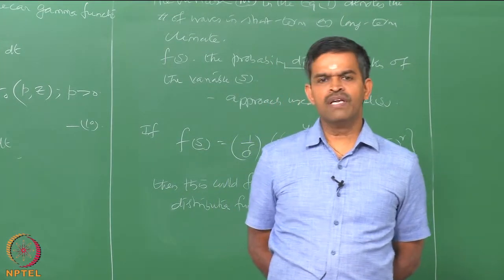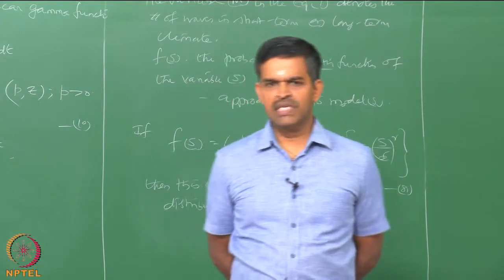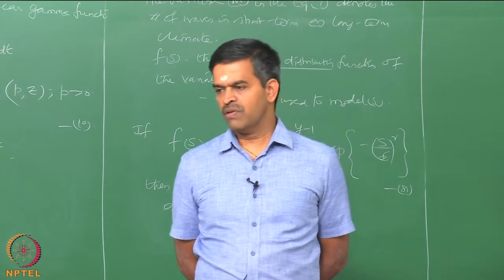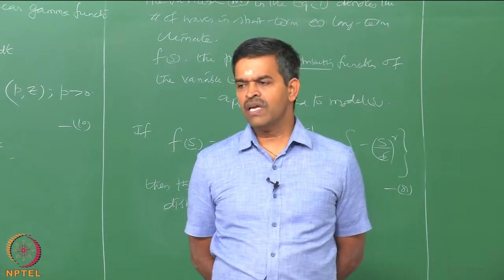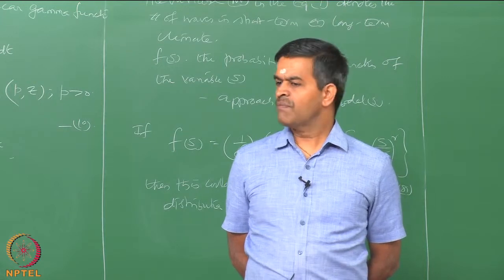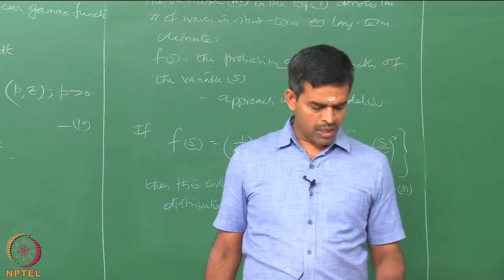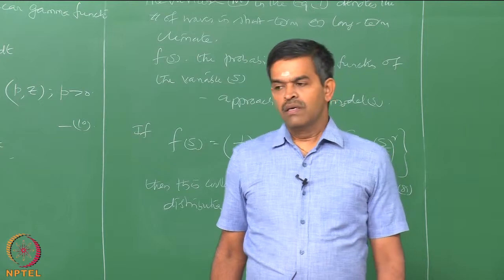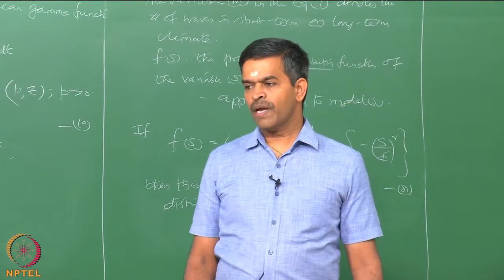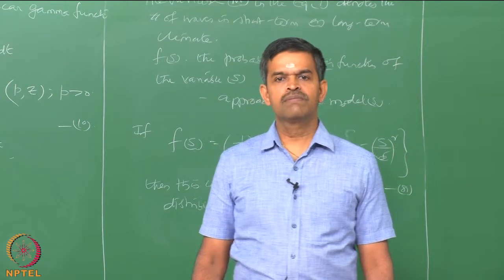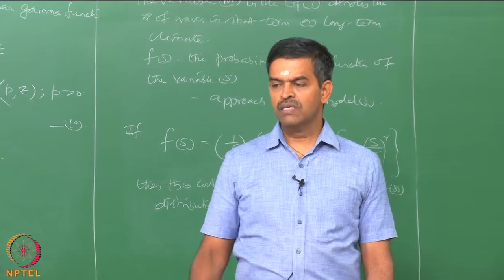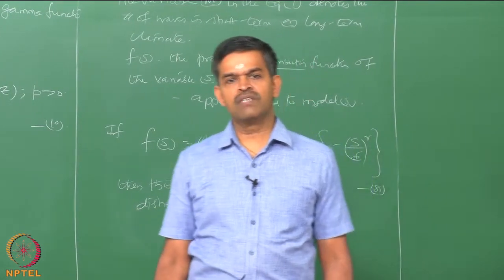Therefore, the basic fatigue data which is used in developing the SN curve is actually the source of large scatter for these variations. So, fatigue damage models, especially under random stresses, can be only approximate, it cannot be accurate. There can be defects and discontinuities at welded joints which can complicate this process of estimate further, because the crack initiation and propagation depends upon the discontinuities at the point of origin of this fracture.